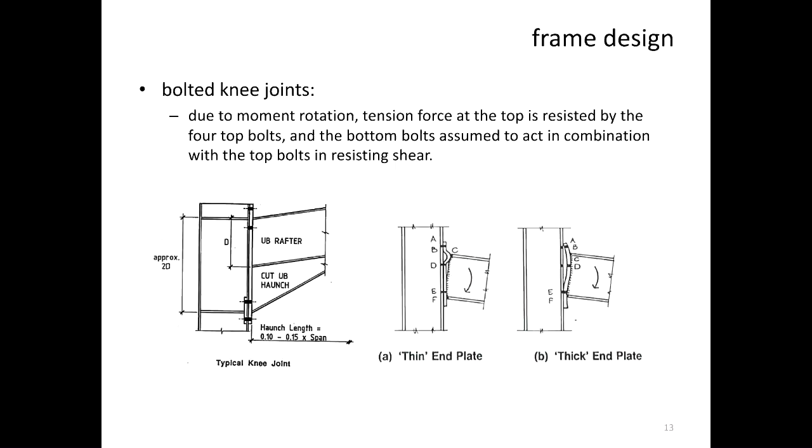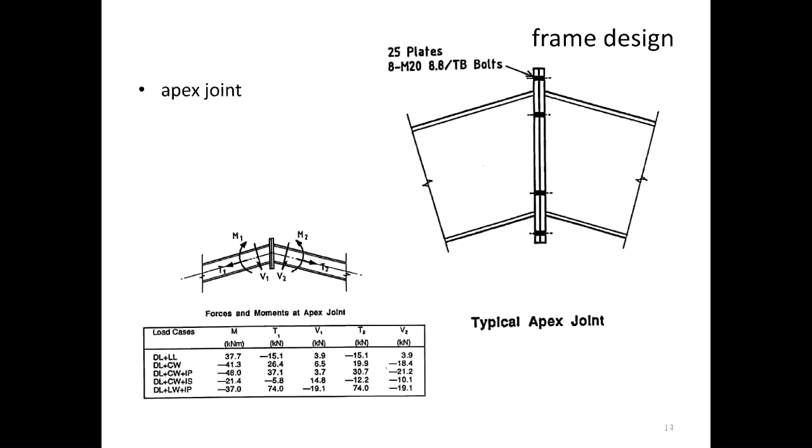At that connection. So please, when you go to sites, if you look on LMS, I've already put the brief, which I will talk about shortly. There are no number of bolts given in the brief. So you have to make sure you count the number of bolts that you found on site. I never said this before and people get the assignments wrong because you lose marks for that. When you annotate your sketches, you don't just say M20 bolts. You have to say 4 M20. So please remember that, but we'll talk about that shortly.